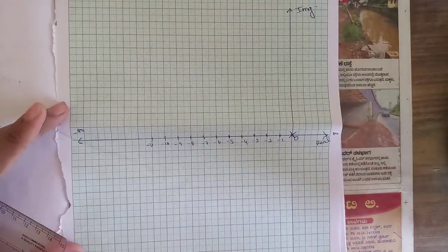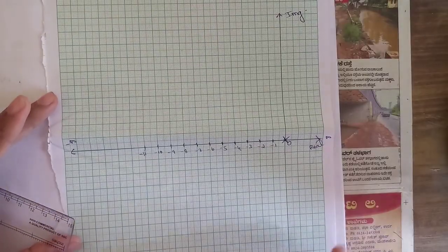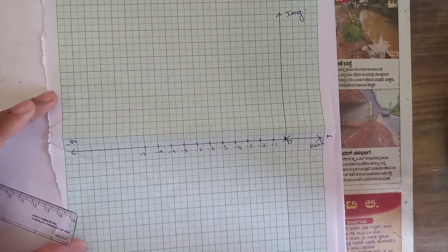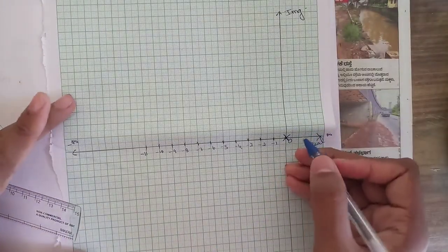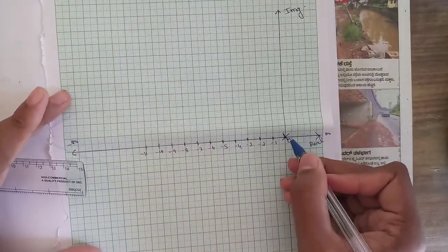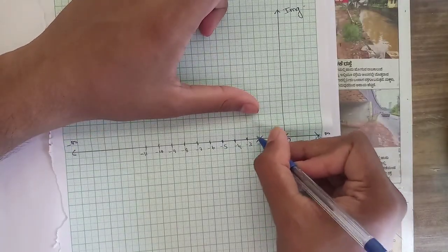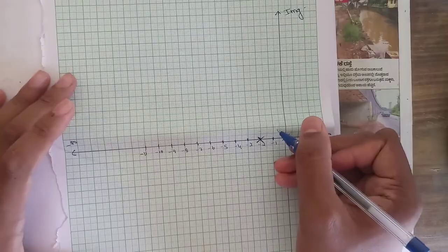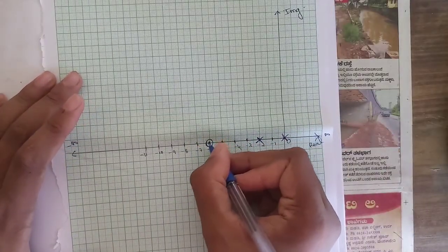This is the rough plot here. I have not written any values for the imaginary axis because we don't have any point of intersection, so the imaginary axis is of no use in this case. Now let's mark the poles. One pole is at the origin 0 and the other pole is at minus 2, right? And we have one more zero, that is at minus 6. So mark that zero as well.